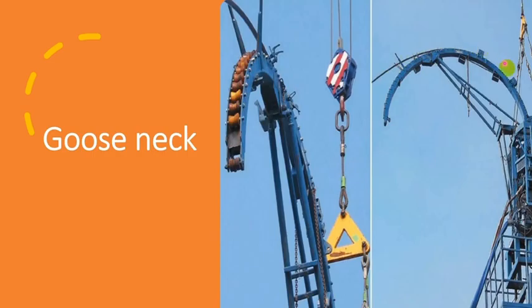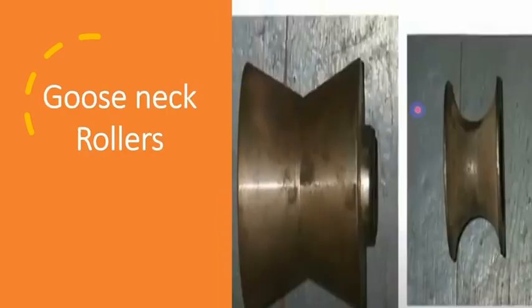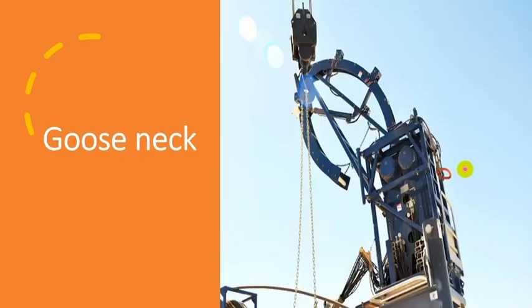It goes around the gooseneck, so it is bent to a specific diameter so bending stresses are not high. Also, it moves around rollers. As you see, these are rollers that reduce stresses and friction between the gooseneck and coil tube.